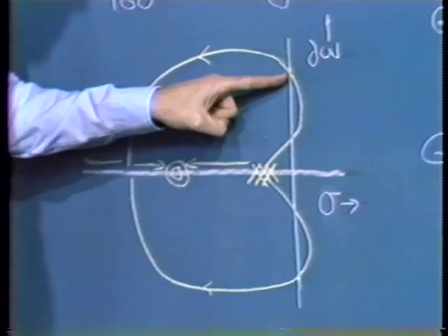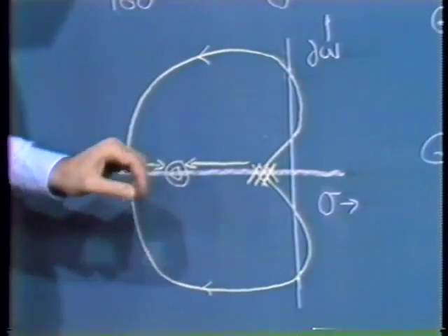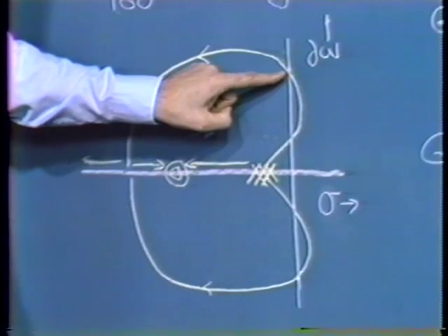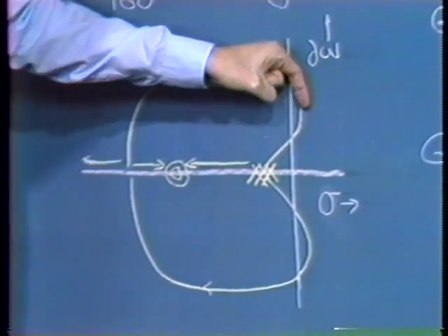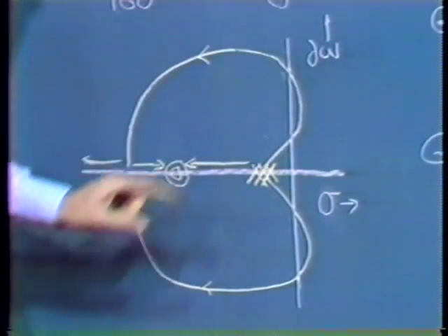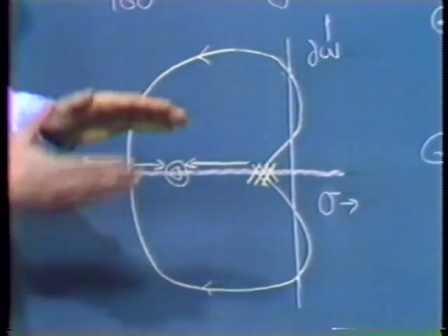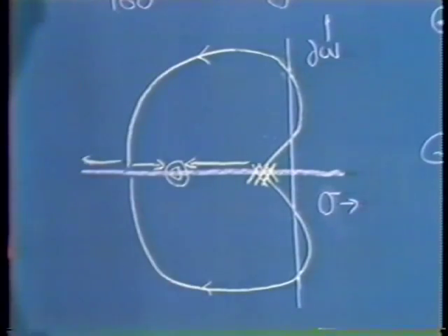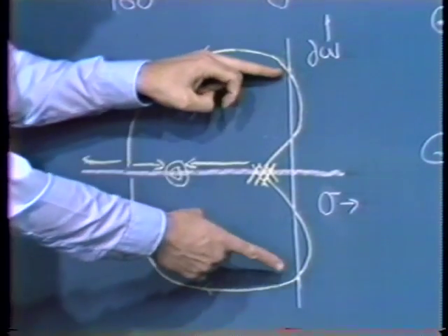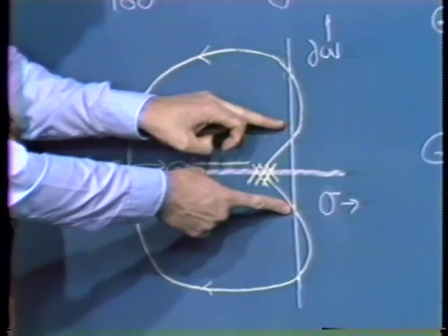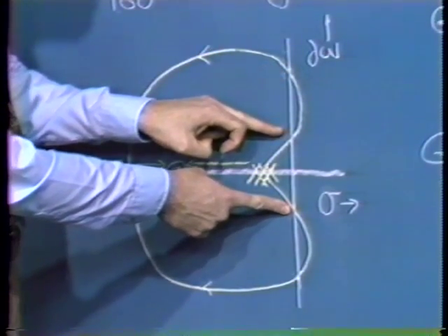Again, if we make the test at this intersection, if we assume that the amplitude increases, the gain drops, the A0 F0 product decreases, we have a system that has poles in the right half plane. Consequently, the amplitude further increases. Once again, the same result. A stable amplitude oscillation is not possible here. A stable amplitude oscillation is possible here.